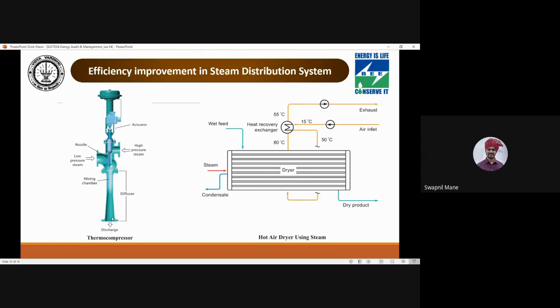The thermocompressors are designed to accurately mix lower pressure steam with higher pressure steam. The higher pressure steam, the motive steam, enters the low pressure steam and increases its pressure. The motive steam is introduced through a nozzle of the compressor. As the nozzle opens, the high velocity motive steam draws the lower pressure steam into the thermocompressor body.